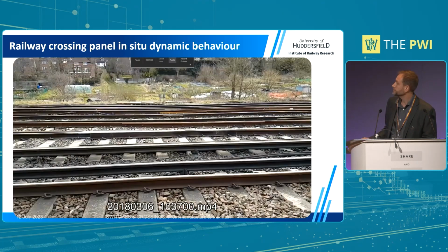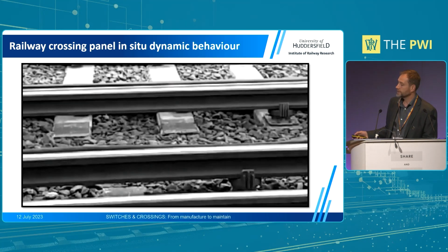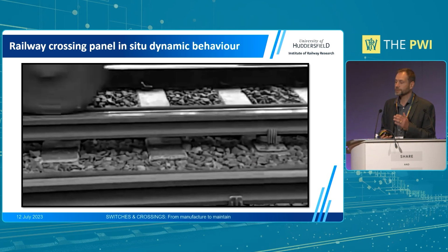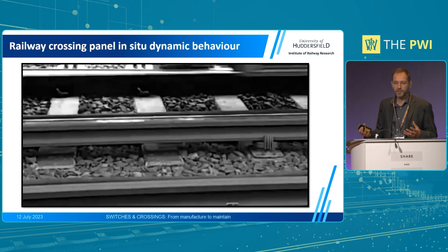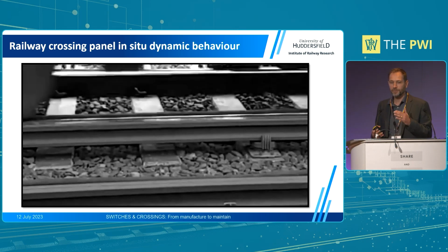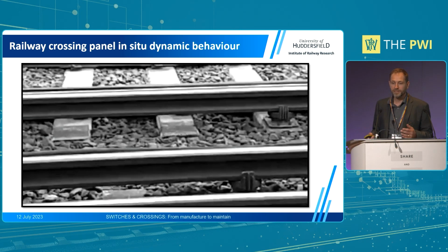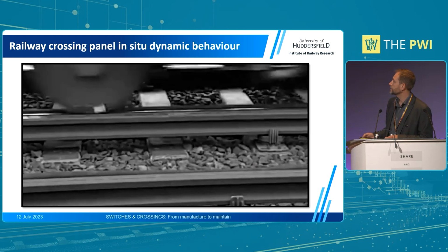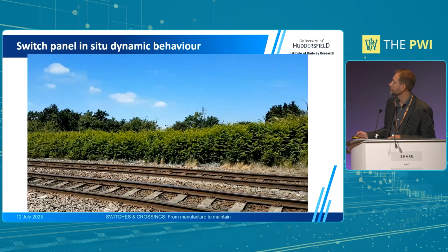this specific casting. If you look more closely, this is the same video but zoomed in, so you can appreciate the movement a bit more. If you simulate the ideal condition of the design, you should have about 1 millimeter of deflection by design, but in reality you get a lot more, and eventually that can lead to a number of problems.